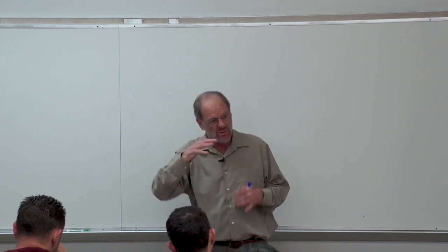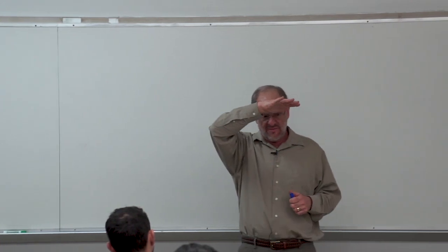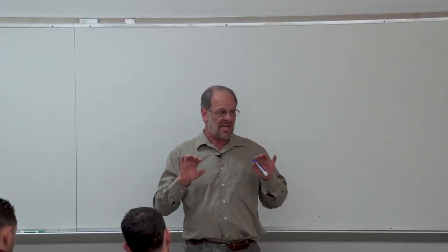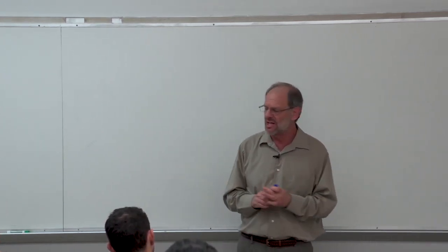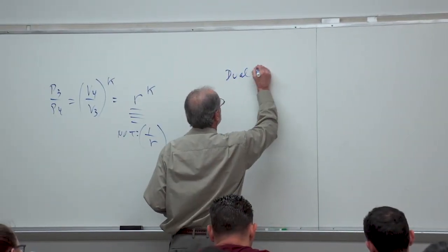But then the heat input is going to continue even as the piston moves. So you're going to have constant volume followed by constant pressure heat input in a more realistic or modern diesel engine. And in that situation, we would use what's called the dual cycle.